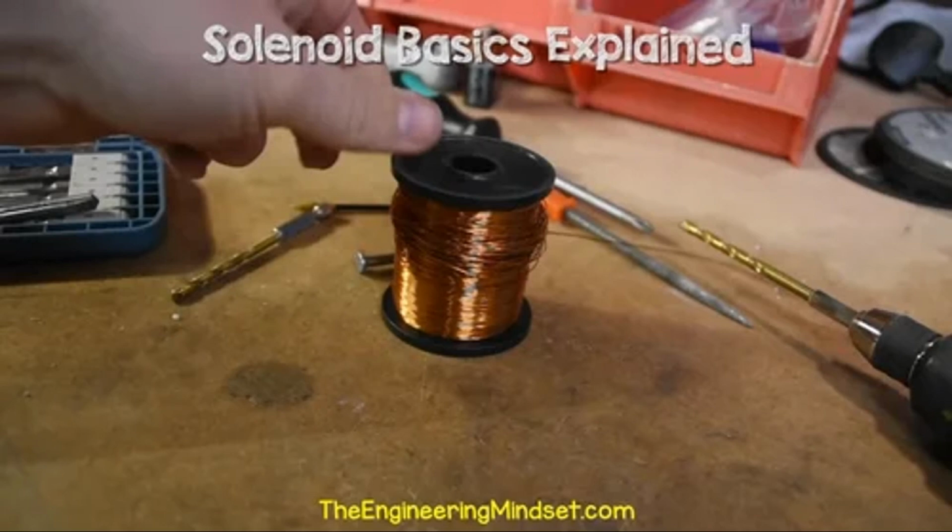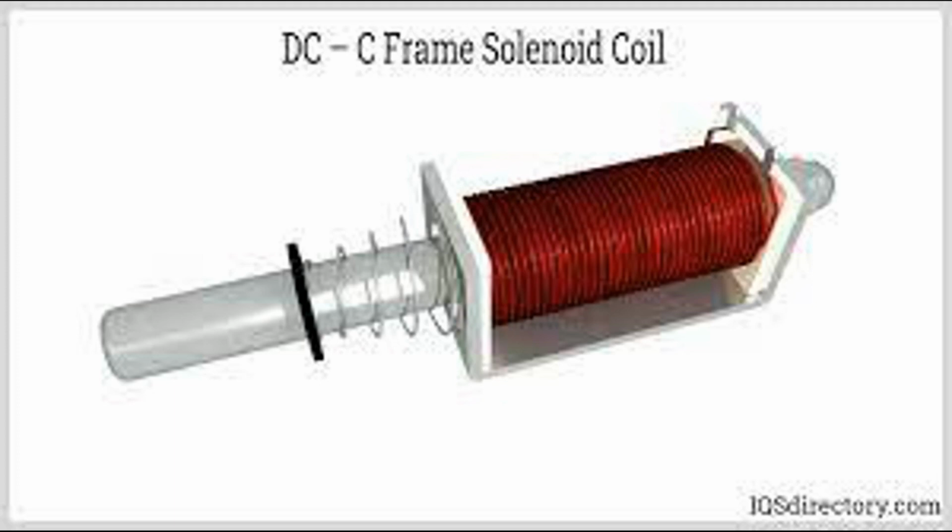Control methods. Rotary solenoids can be controlled using various methods to achieve the desired rotary motion. The control methods can vary depending on the specific application and system requirements. Here are some common control methods used with rotary solenoids. Direct current (DC) control. One of the simplest control methods for rotary solenoids is to directly apply a DC voltage to the solenoid coil. By energizing the coil with a specific voltage and current, the solenoid generates a magnetic field that causes the desired rotation. The rotation can be stopped by de-energizing the coil.